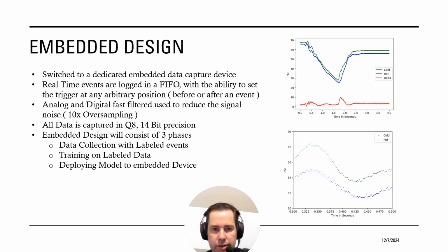To fix this, I developed a triple-core processor, one ESP32 for machine learning, an RA ARM chip for the ADC, and a micro real-time clock for data timing. I created a dual-channel rolling FIFO with a variable trigger to capture both before and after the first pressure wave was seen by any sensor. I then took a day walking around my house, turning on and off every faucet dozens of times to generate labeled training data.